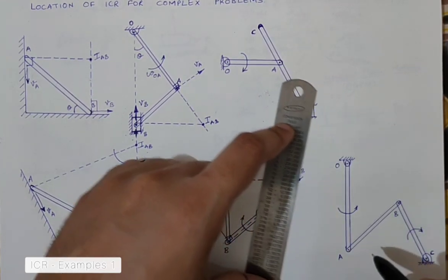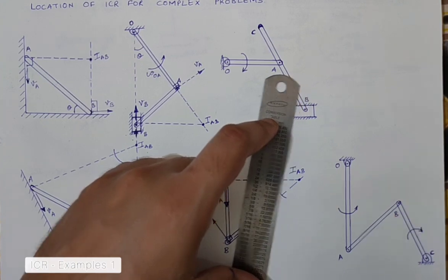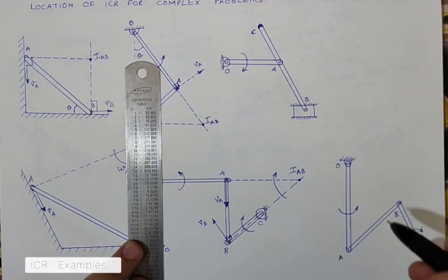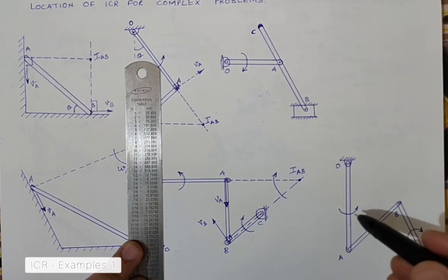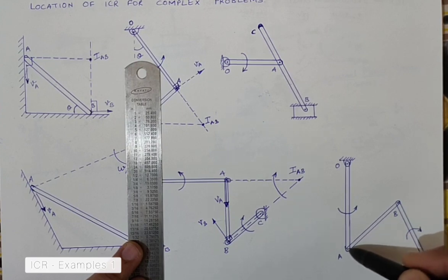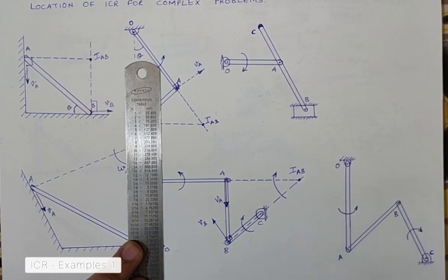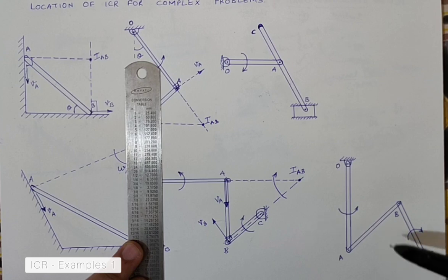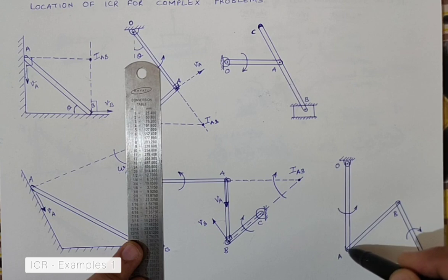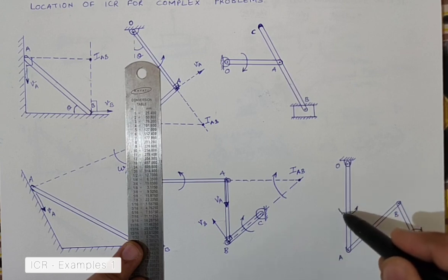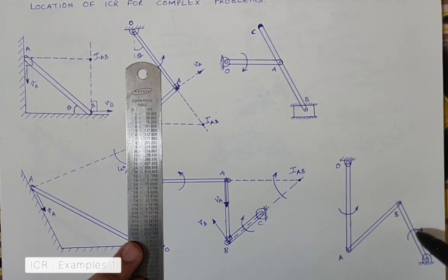general plane motion. So general plane motion, okay, yes, before we proceed further, there might be a question in someone's mind: why is AB under general plane motion when the point A is also rotational and point B is also completely rotational? So in this case, the answer is that point A is under rotational motion, which is for sure, but it is at different angular velocity. Same is the case of point B, which is at different angular velocity.